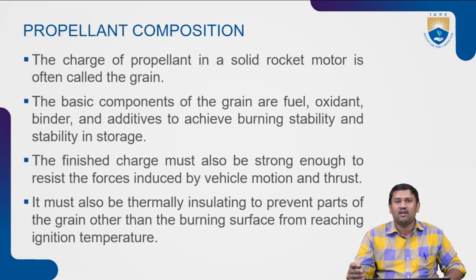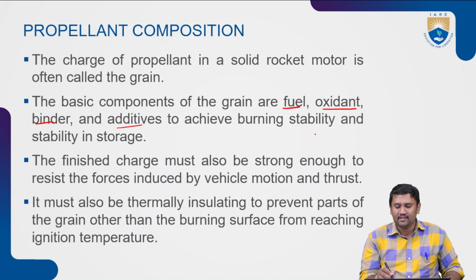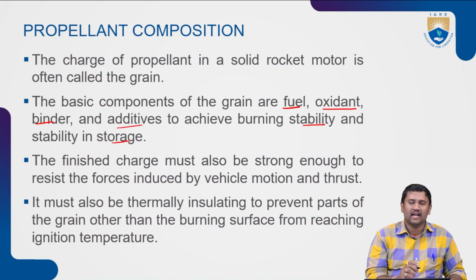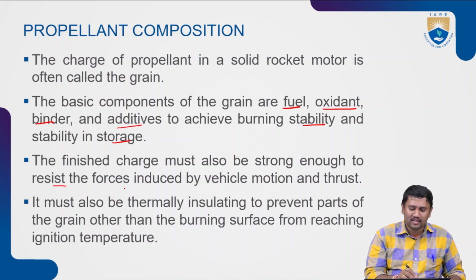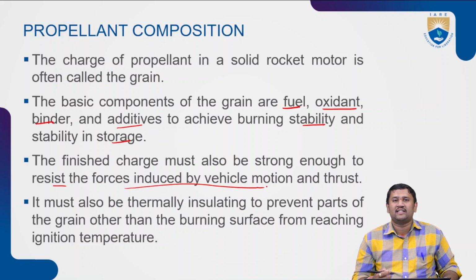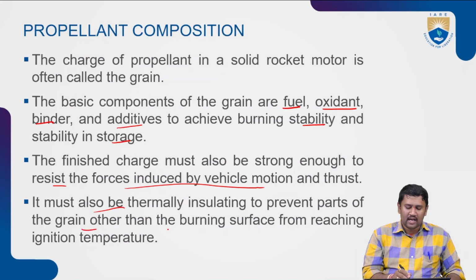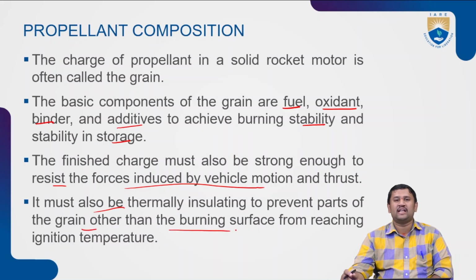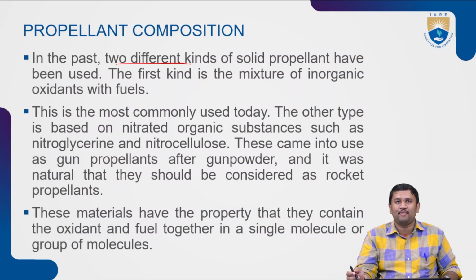The charge, or the fuel block, of the solid rocket motor is often called the grain. As we know, the basic components of the grain are fuel as well as oxidant primarily, and binder as well as additives to achieve burning stability as well as stability under storage. The finished charge must also be strong enough to resist the forces induced by the vehicular motion and the thrust. It must also be thermally insulating to prevent parts of the grain other than the burning surface from reaching the ignition temperature.